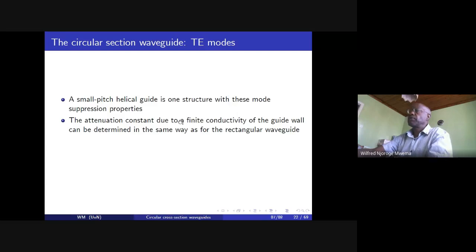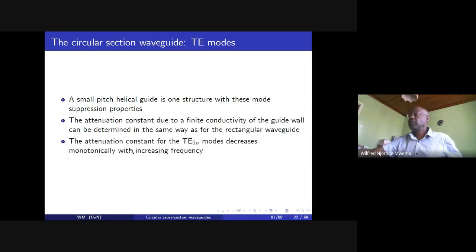So the attenuation constant due to the finite conductivity of the guide wall may be determined in the same way as in the rectangular waveguide. And the attenuation constant for the TE0n modes decreases monotonically with increasing frequency.